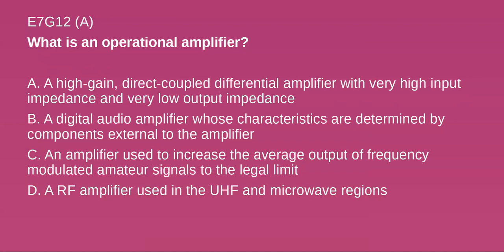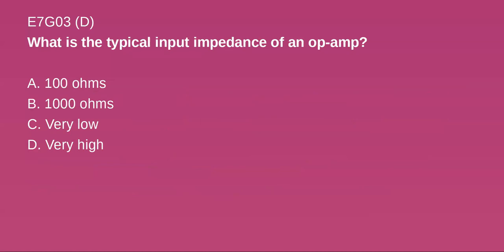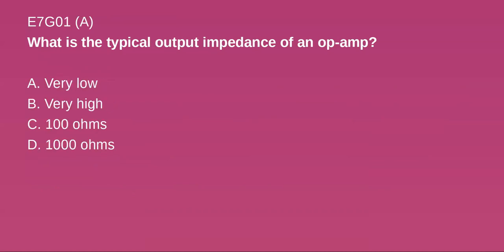So what is an operational amplifier? Differential amplifier, that's what we just talked about, right? Sound good? Yeah. What is the typical input impedance of an op amp? Very, very high. What's typical output impedance? Very low.